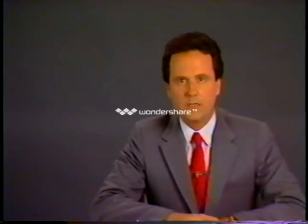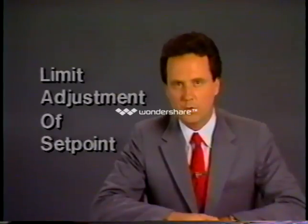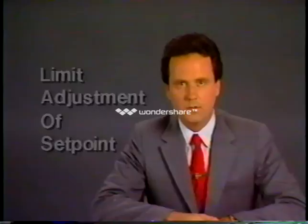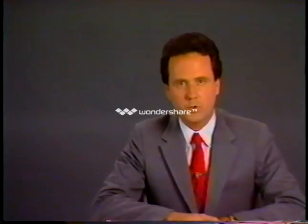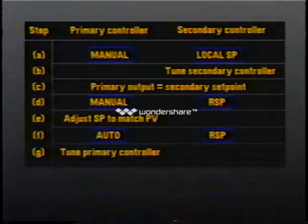In order to protect the process, it may be necessary to limit the amount of set point adjustment on the secondary controller made by the output of the primary controller. This can be accomplished by limiting the maximum and minimum output of the primary controller through the adjustment of the output limiting devices. Because cascade loops are by nature interactive, a specific procedure should be followed for tuning and startup.